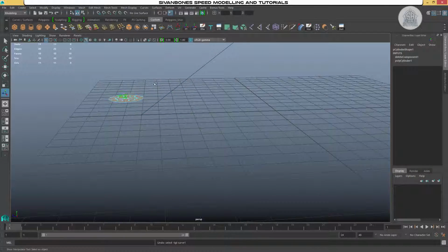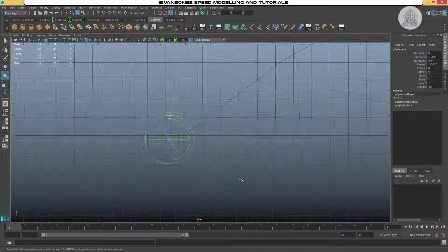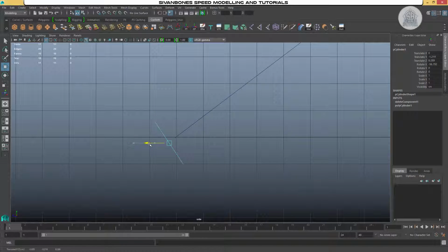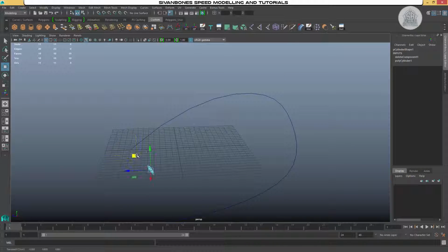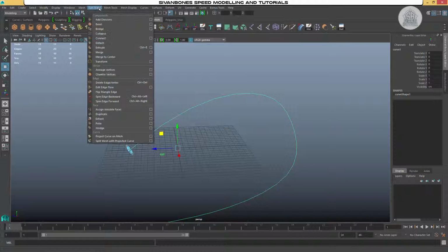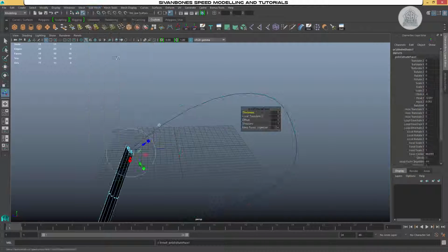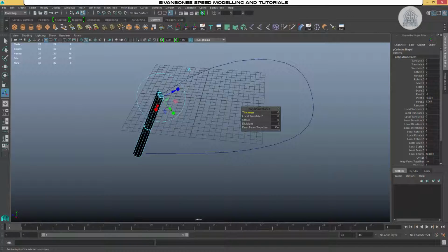So what you normally want to do is move the geometry and get it roughly going the right way of the curve. So I've put it roughly here at the start. If I now go to faces, select, shift-select the curve, and edit mesh, extrude. By default it should recognize that you're going to extrude along a curve, so you shouldn't have to worry about those settings.